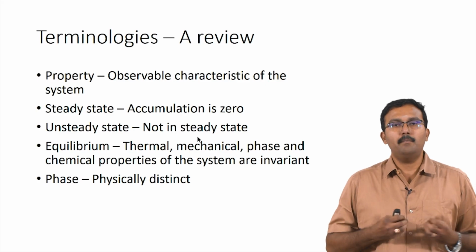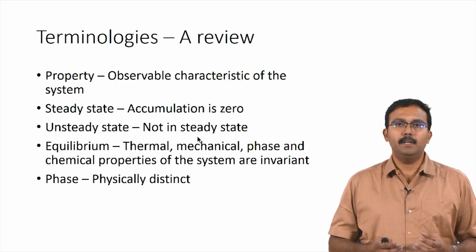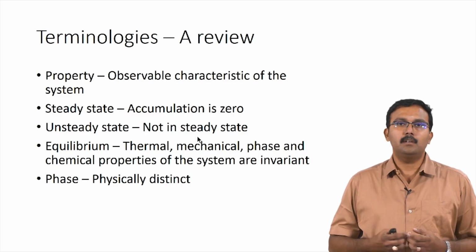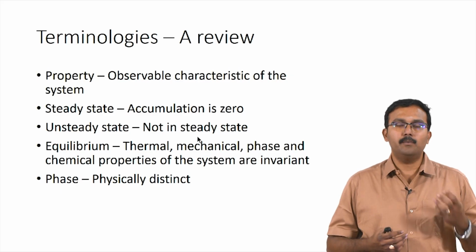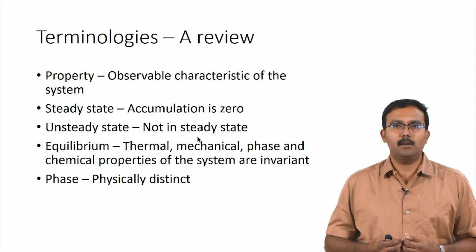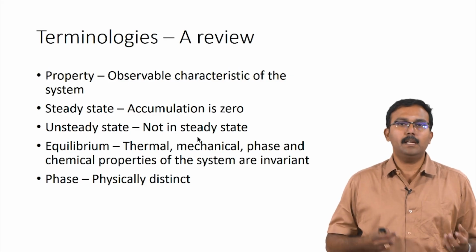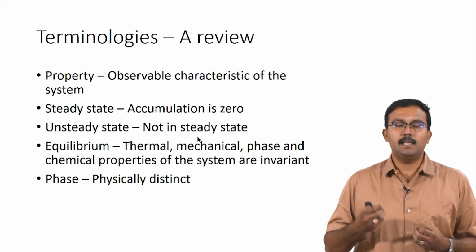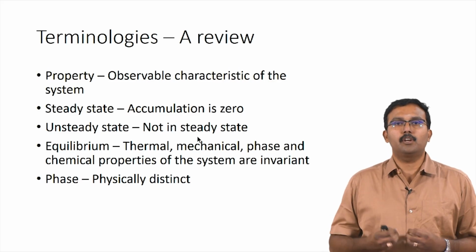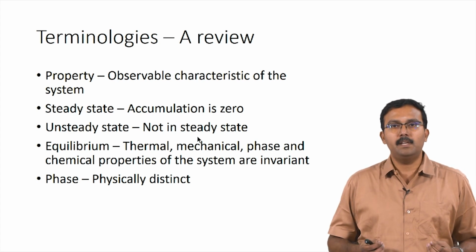Until now, when we performed material balance calculations, we were only looking at each component based on its chemical identity. So, water was not distinguished between water liquid versus water vapor. However, when we perform energy balance calculations, it is important for us to distinguish between water liquid and water vapor, because there is energy associated with phase change. Hence, phases of the components which are involved in the process have to be looked at carefully when we perform